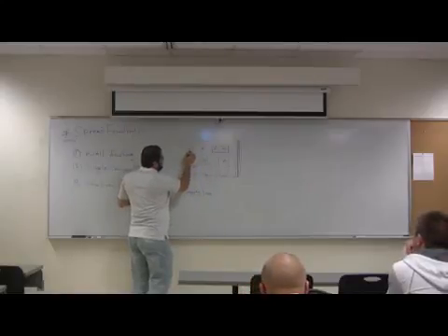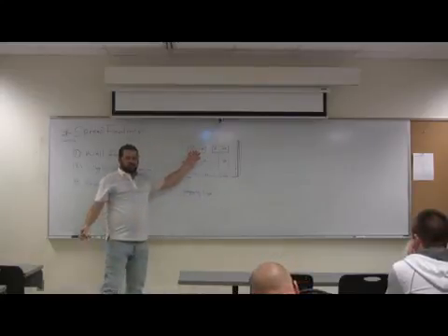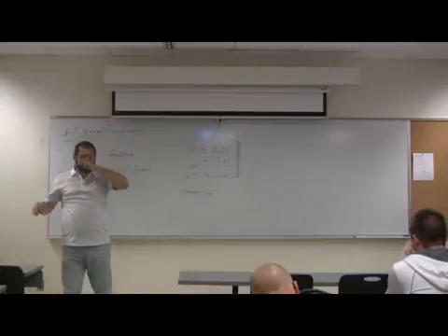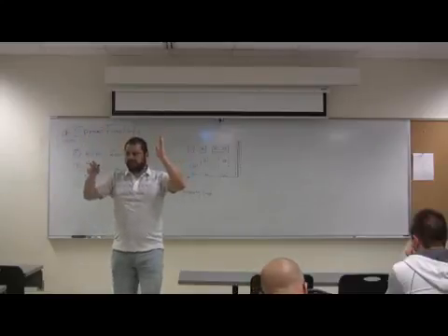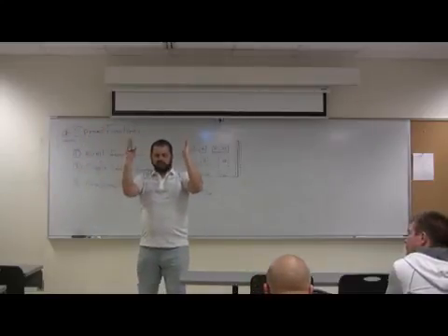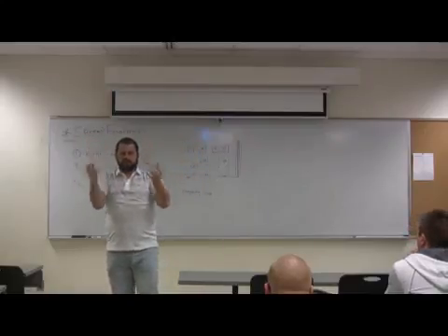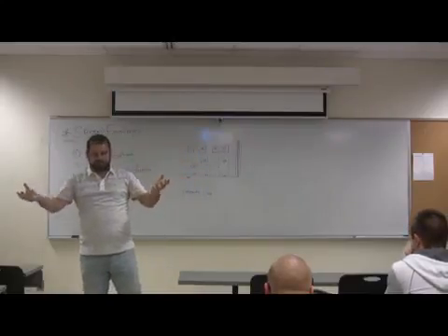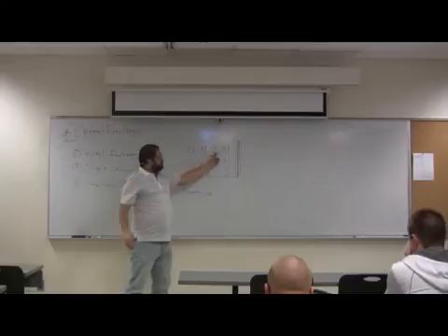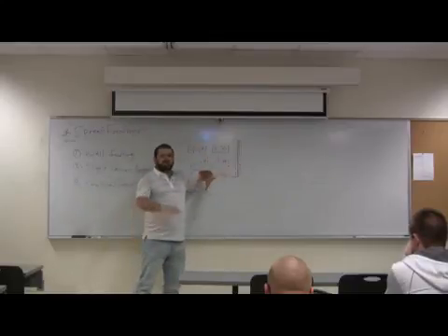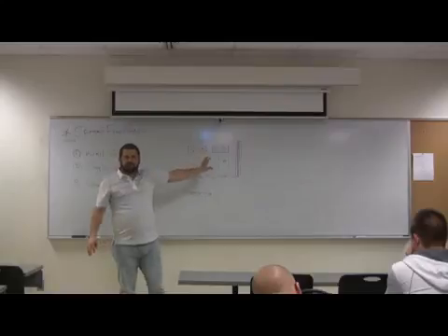Sometimes we can combine them like this. It's called strap footing. We connect them together. Usually this is the case when you have a moment frame, or concentric X bracing, so you want this frame to work together and resist the lateral load. So you try to tie those footings together after you design the required footing for each of them. This is called strap footing, combined footing, single column footing, wall footing. All of these are called spread footings.